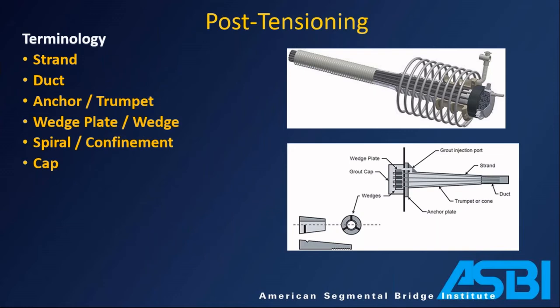So a quick rundown on what some of those parts and pieces are. You have strands. So you have individual strands of tendons. Each strand is usually composed of 7 wires. And one strand is, ballpark, the diameter of your finger, maybe your thumb. Multiple strands create a tendon. You have them anywhere from 4 strands up to 30-ish.